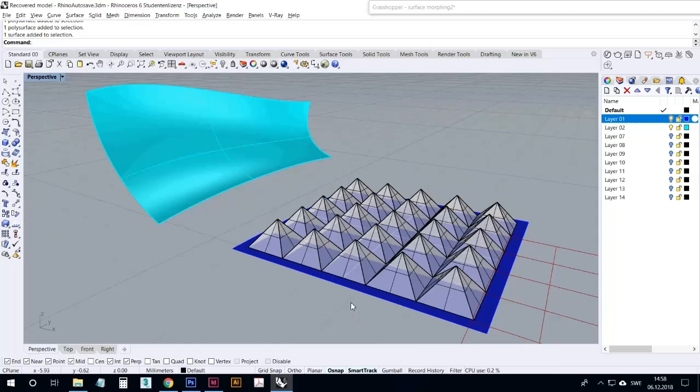I'll show you first how to do this in Rhino, so flow along surface. If you see up here I'm typing, and also the input objects in Grasshopper actually correspond to the command line up here. So it's going to ask you questions and then you're going to simply answer them. So flow along surface, a question comes: select objects to flow along a surface.